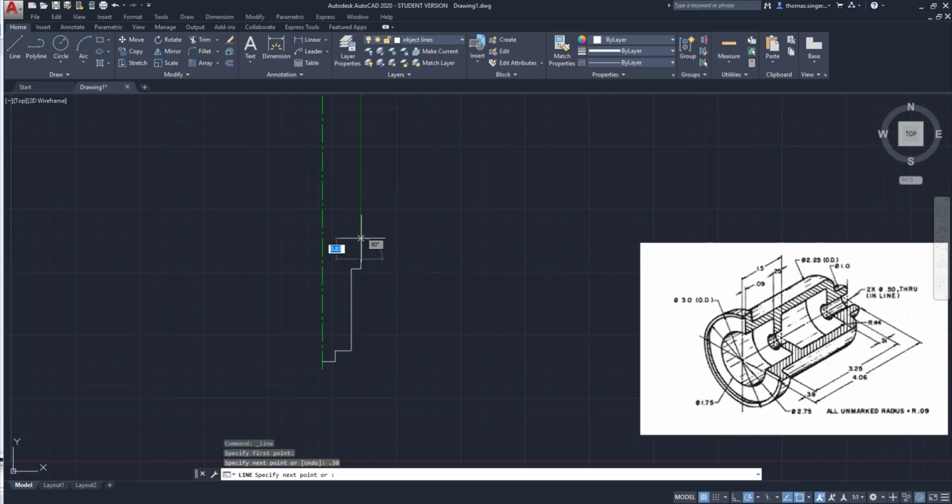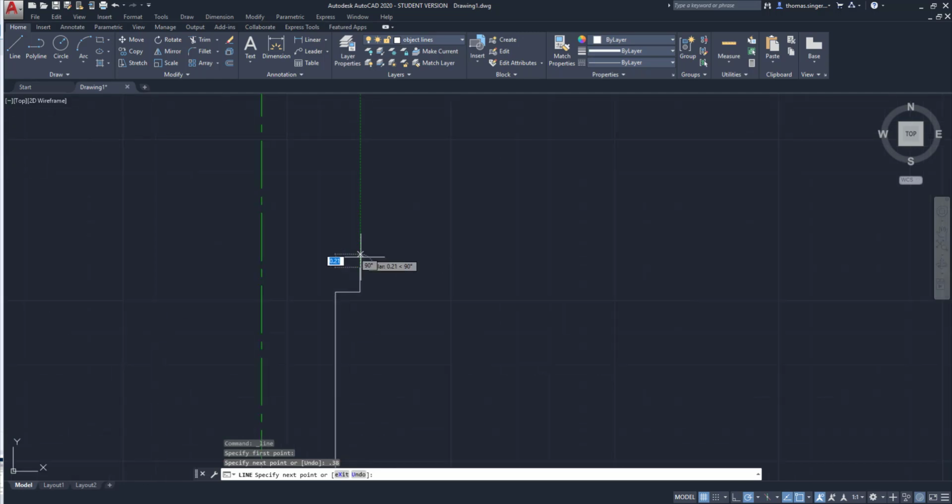0.38, go vertical. Now we're going to need to magnify because we have a very small lip here. So the inside diameter is 2.75, so the difference is basically 1/8 of an inch thickness between the outer and the inner diameter. And then we have a depth of that section of 0.09. So let's magnify up. So it's going to be 0.125 and then 0.09 down. And then that's going to go to the hole.